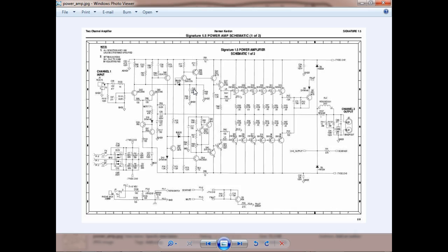But you won't see any saturated switches. These are not saturated switches. These are all in parallel, by the way. And we'll talk a little bit about that. This gives us the ability to control a lot of power, because what we do is we divide that power over 6 transistors. So if each one of these transistors was handling 20 watts, then that would be 120 watts that was hooked in parallel like that. So if we hook devices in parallel, we can increase the current, or reduce the current through one, basically because they're shared. So one of these would be the left channel, one of these would be the right channel. This is the power amp.